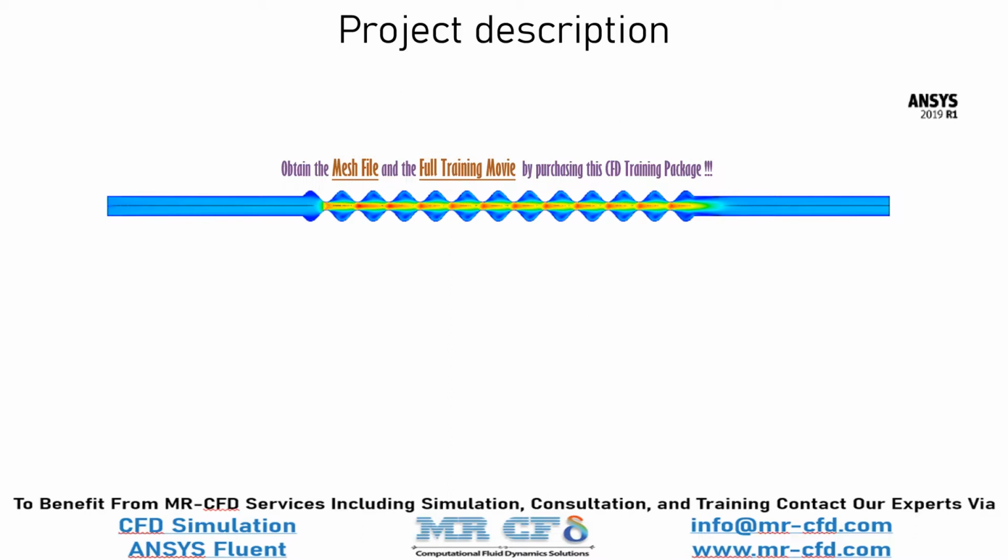To perform such steps, the plate silencer has some plates inside itself. By adapting their mode shapes due to the vibration caused by the sound waves, the plates absorb the sound. These mufflers are used in various industries such as metallurgy, power, mining, etc. The material and the type of design of the silencer are such that they can absorb the sounds produced with different frequencies and in the range of human hearing from 63 to 800 Hz. They can provide the condition of environmental comfort in terms of sound.